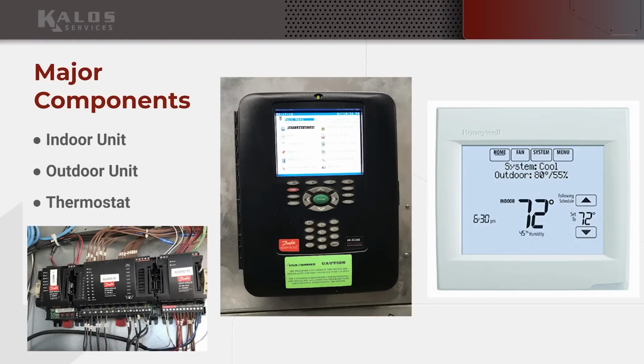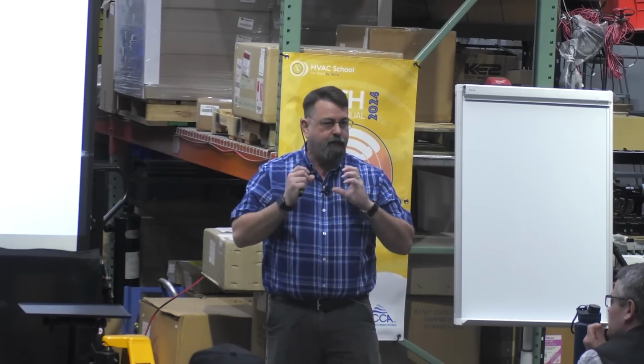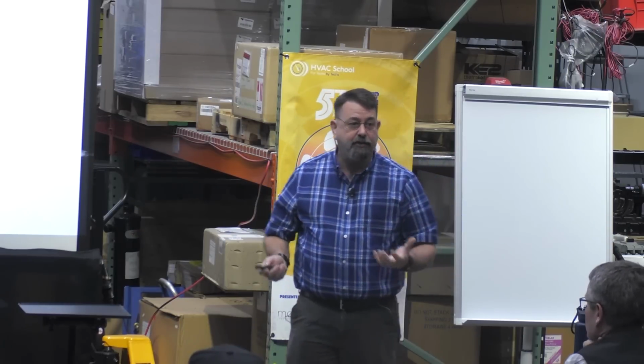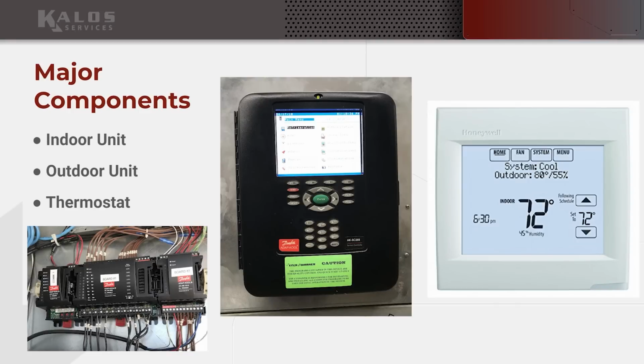Then I've got a decision maker. I've got a computer that's comparing those inputs to the values that I want, my temperature setting, 72 in this case, right? And deciding what to do about that. It's making a decision. So I've got a decision maker who's going to read those inputs and decide I need to take action or not, okay? And then it's going to turn things on and off, right? Well, that's its outputs. So I've got inputs coming in, I've got some decision making going on, and then I've got some outputs, right? That's really what my thermostat is doing.